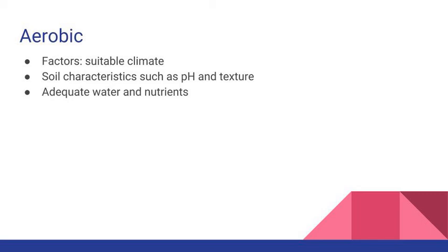Facilities with strong evidence of natural attenuation are good candidates for biological remediation. Biological remediation is also considered at facilities undergoing groundwater pump and treat remediation, by accelerating the rate of remediation with in situ enhanced dehalogenation, or as a replacement of the pump and treat when the contaminant concentration reaches an asymptotic level that exceeds the remedial goals.